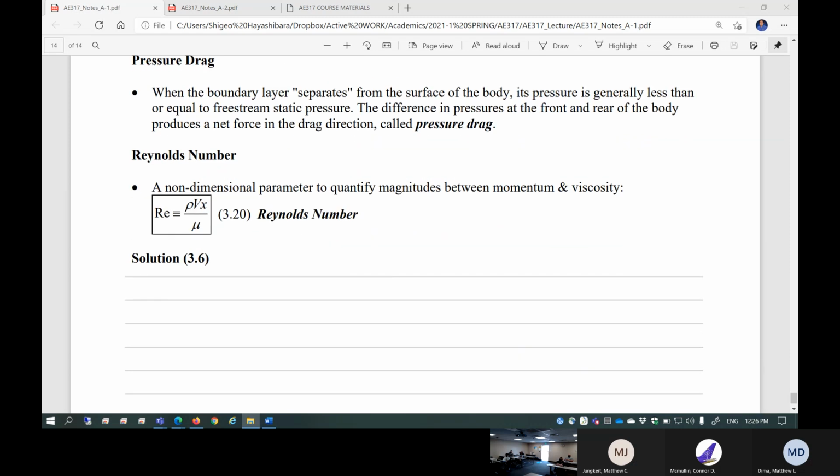Reynolds number is used to predict the transition. There is something called the transition Reynolds number, which is a quite important parameter when you run XFLR5. In other words, you can define the transition Reynolds number all by yourself, or you can force transition at certain chord lengths, or you can avoid the transition at all. You can control those things, right?